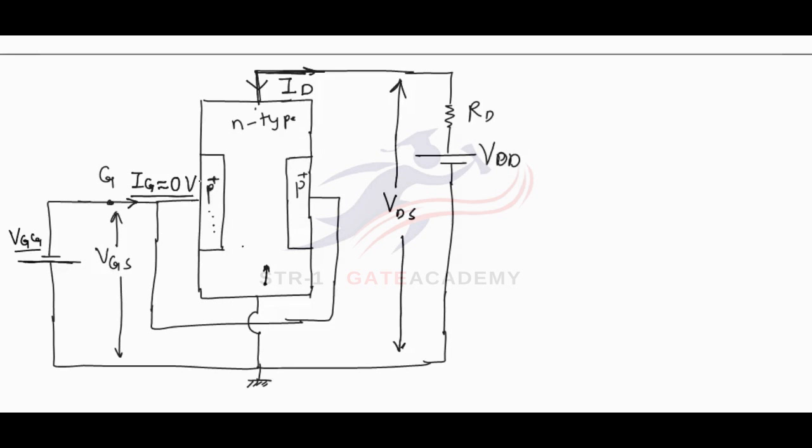Now this voltage of VGG, for example, is at some voltage -2 volt, because with respect to source it is negative, and source is grounded, means it is at zero potential, and with respect to source drain is biased at higher potential, means it is somewhat at +5 volt.